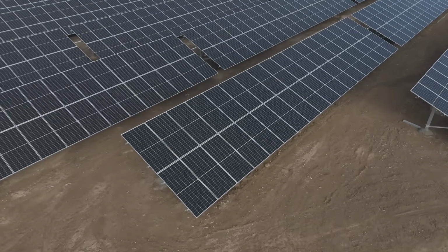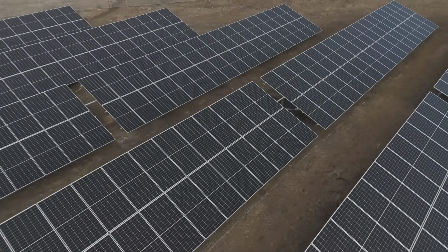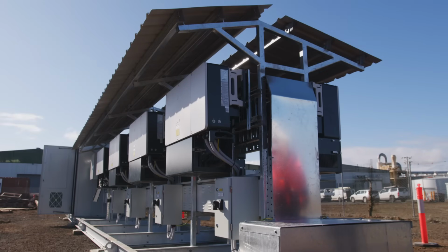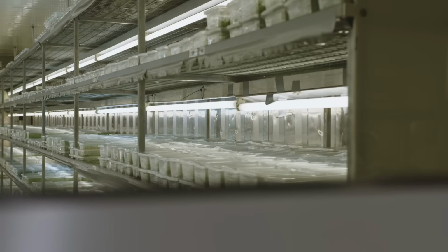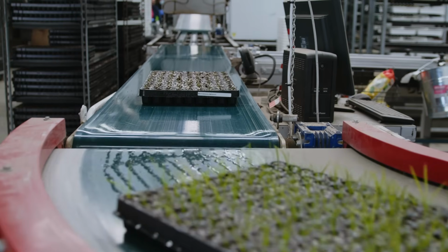Yes, if we are doing the protection coordination study particularly for the solar, we would want the solar breaker to trip first rather than the existing infrastructure. Because the last thing a business owner wants is, let's say they've got a production line, for it to suddenly fail. So the solar is the sacrificial lamb in a way, isn't it, when it comes to these protection studies?